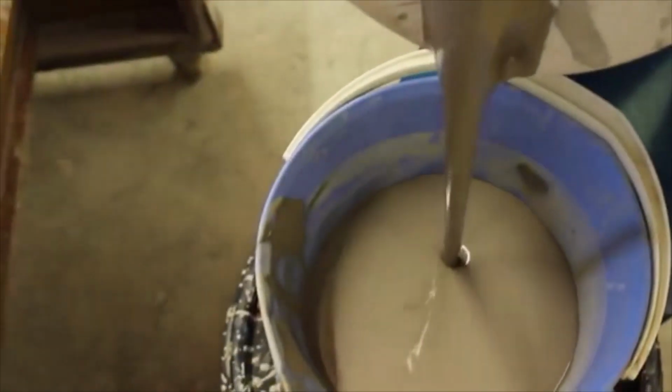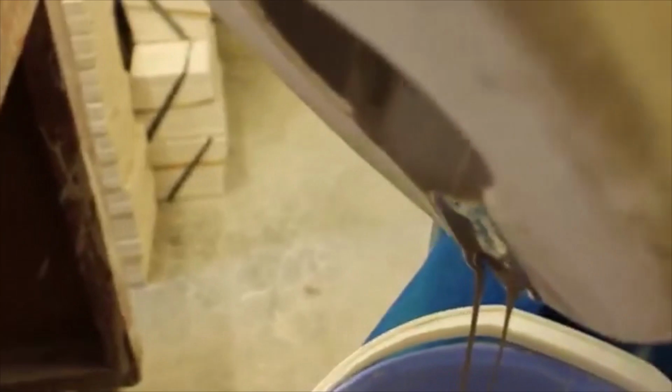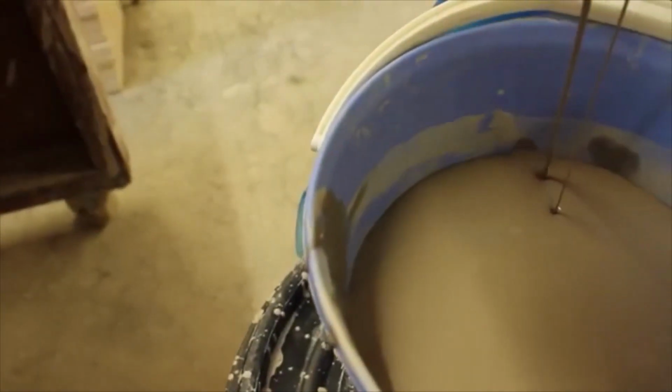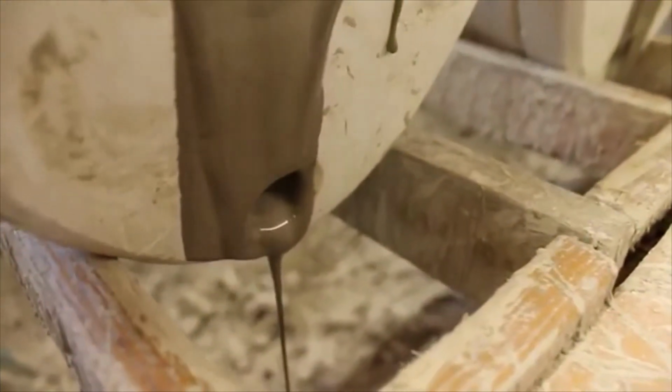Because the clay dries quicker to form a solid at the edges of the mould, tipping after a carefully controlled amount of time allows most of the still liquid clay to be poured away, leaving the soft but solid layer of clay around the outside. At this stage, timing is very important. Minutes can be the difference between a perfectly cast teapot and something which will have to be recycled in the plunger.